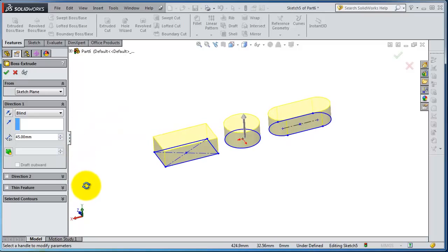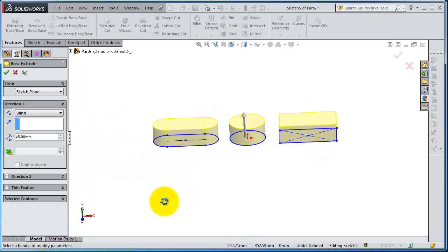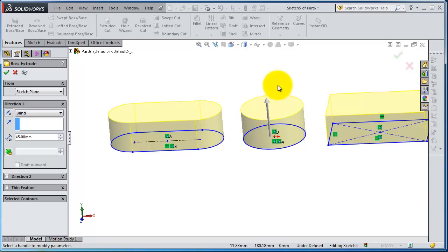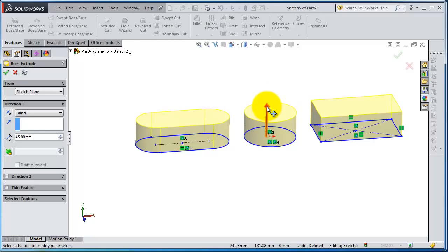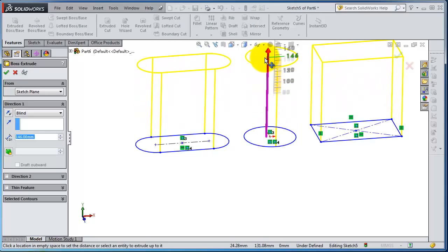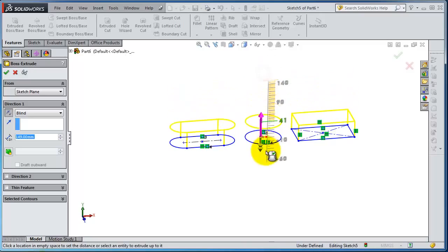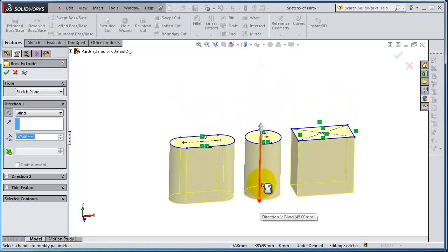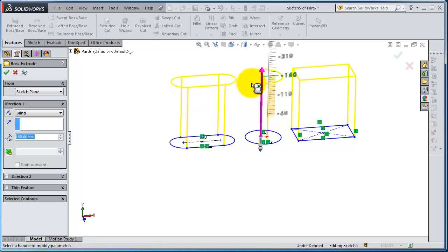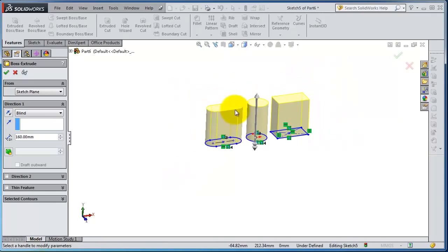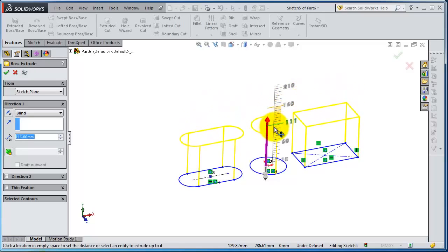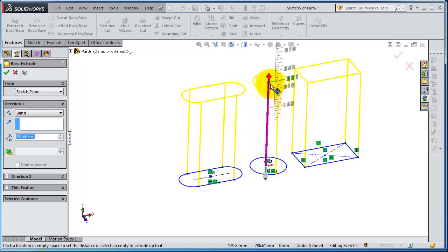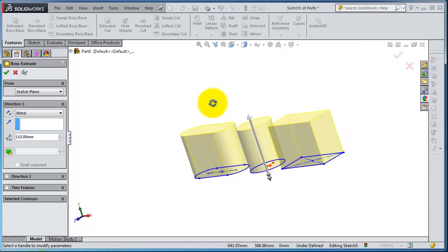All the drawn sketches, and you see this arrow. This is a quick extruding option. When you select that arrow, you are able to expand it or change its direction downward. So it's a quick way to create an extrusion. And sometimes you need to make some quick solid models without having exact dimensions. So that is a quick way to make it.